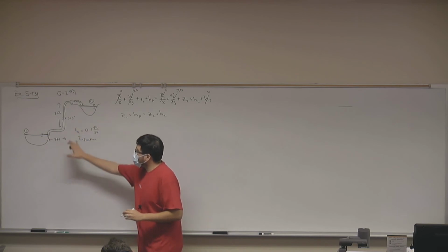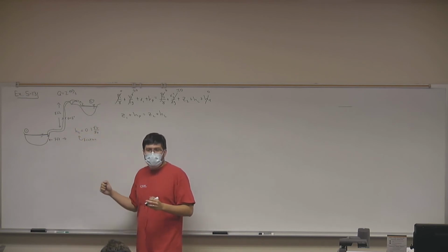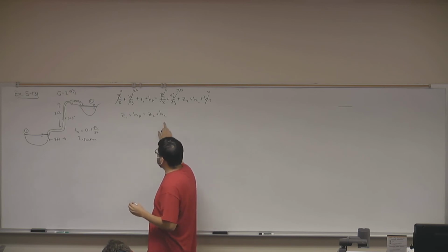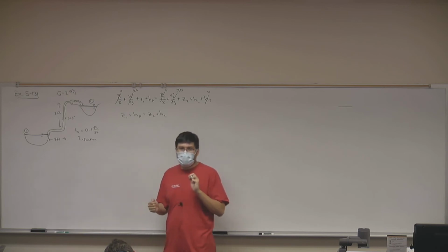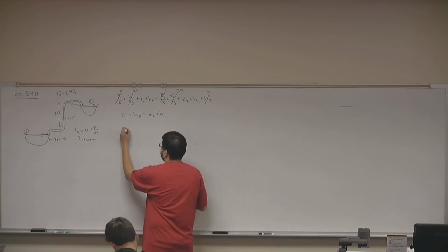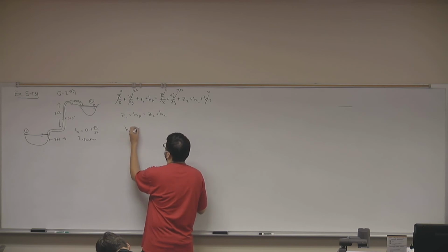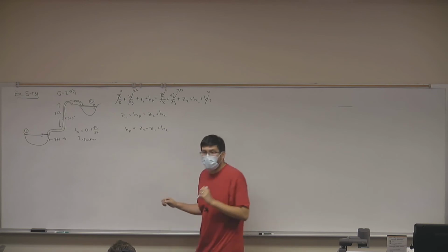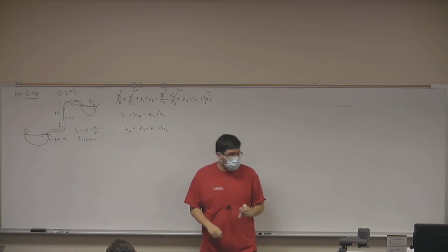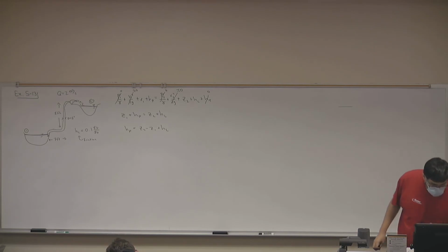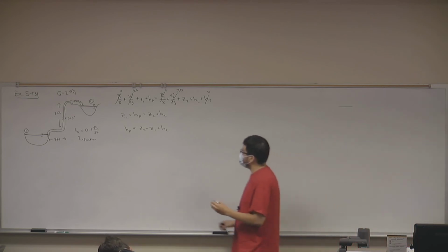What was the point of this exercise? What are we looking for? Horsepower, right? So which of these 4 terms may include the horsepower within it? Pump head. Okay, so let's say that I want to solve for pump head first. I get pump head equals the change in elevation plus my head losses. Do we know the change in elevation? Yeah, it looks like it's going to be 8 feet. Good.